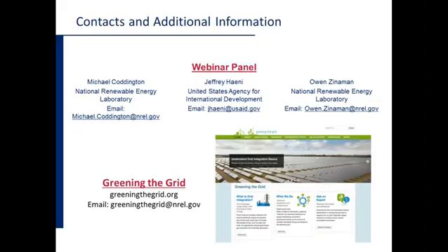And when they do so, they treat everything as if it's energized. They don't have time to make sure that everything's disconnected and that they ground all the lines together, which is the requirement if they were to take off their rubber gloves and their protective devices. So, line people around the world know that they just need to pretend as if the line is energized, or assume the line is energized, and work so that they continue to be safe and they solve the problem.